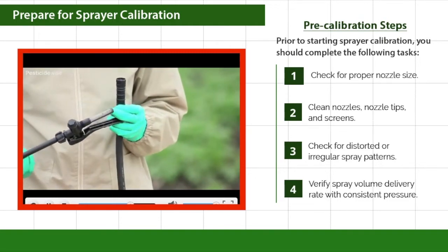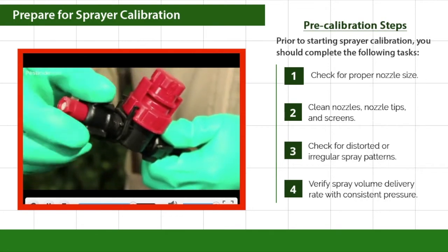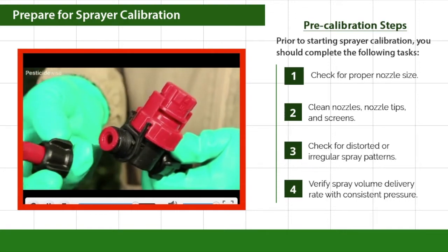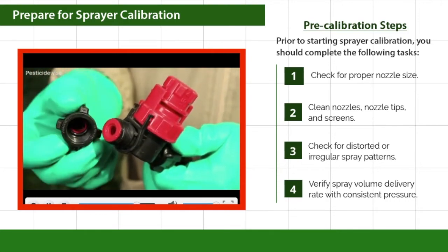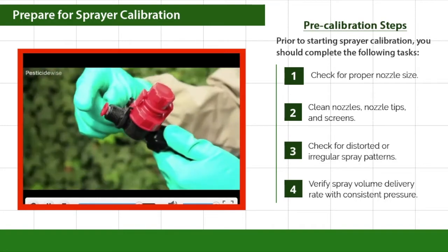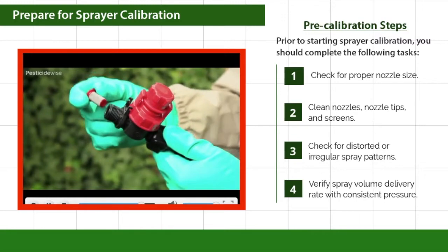If it does not, then it will need to be replaced or repaired. Next, check the nozzle, and if there is damage to the nozzle, replace it. To see how they are fitted, just twist the nozzle cap off, and the nozzle with its nozzle filter and a sealing O-ring can be seen. The filter must be clean as it protects the nozzle from becoming completely or partly blocked.